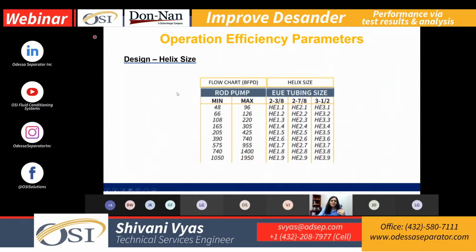And depending on the helix sizes and your tubing size, that is how we size the helix. What is the well history or well intervention, what is the solid particle size that we're looking at, all those factors come in for sizing that helix size. And for example, this was the 1.4 that we saw. 1.4 means that we're dealing with 2 and 3/8 tubing, versus 2 point something is 2 and 7/8, 3 point something is 3.5 tubing. And then obviously the sleeve length.